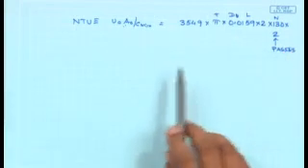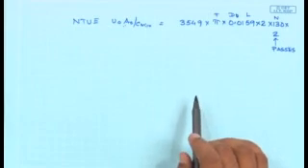Okay. So just be careful while calculating the overall area for heat transfer. The total area for heat transfer would be the outside area of one tube multiplied by the number of tubes per pass and the total number of passes, because when you do that, only then you get the total heat transfer area in the heat exchanger, considering all tubes and all passes.